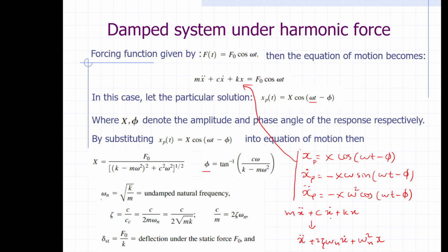So you compare these two. This one you can rewrite as c over m, and this one k over m. Comparing these two, you can find zeta is just the ratio between c and the square root of mk, multiplied by 2, and that's why it's called the damping ratio. Okay,